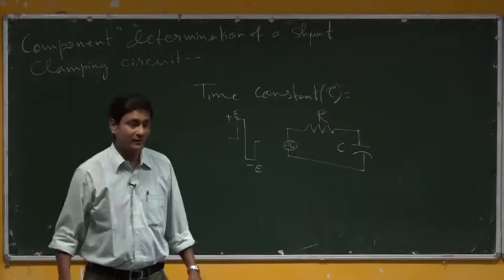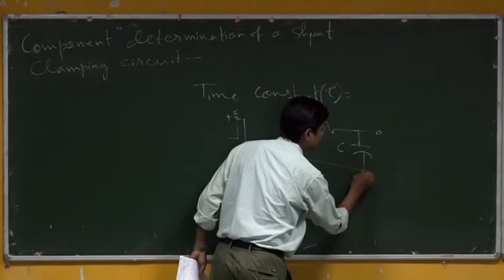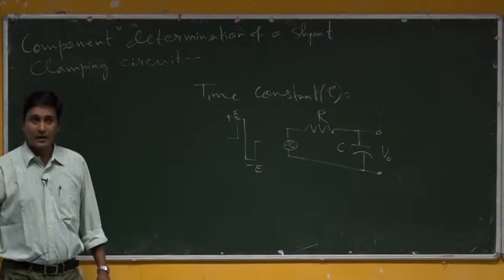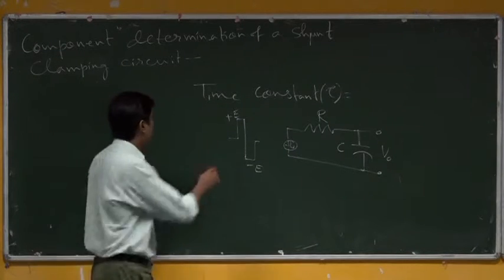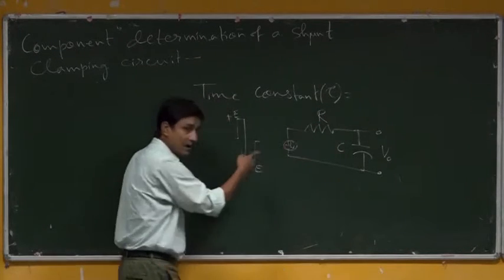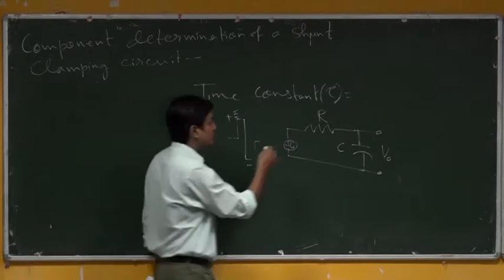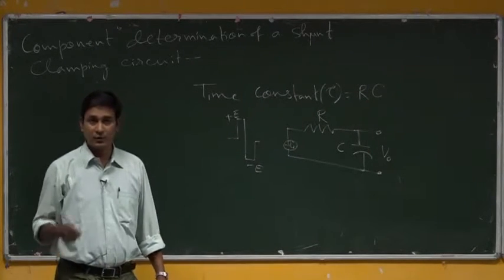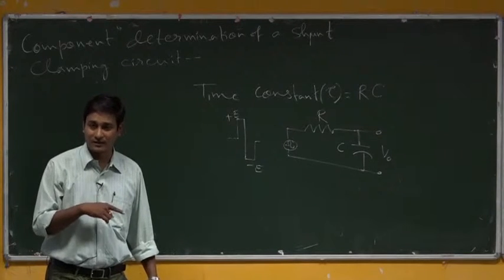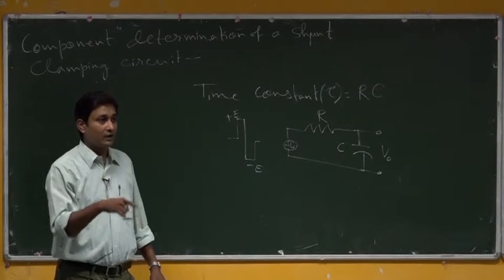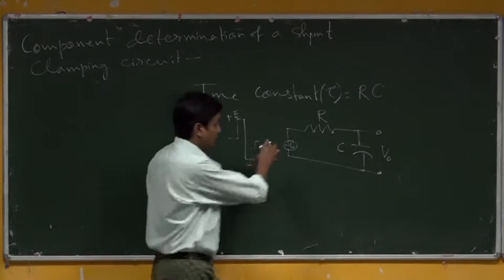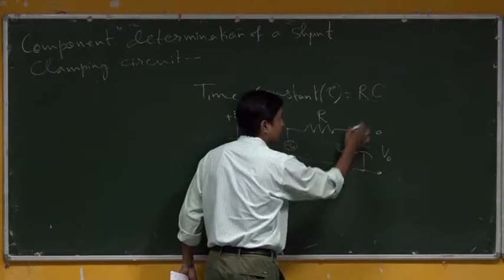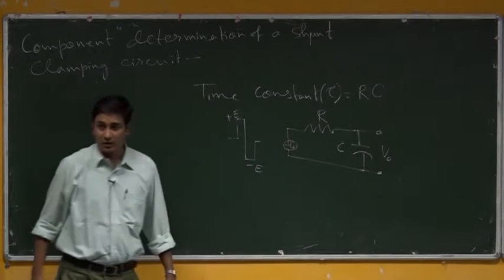Do you expect the voltage across the capacitor will become E? Now, after your idea on the time constant, which in this circuitry is R into C, the way it was found in the last class, if in a circuit the total path has resistance R and capacitance C, the time constant will be RC. What does it mean?